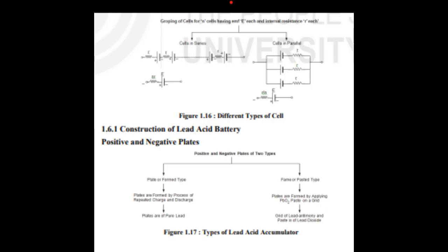1.5.2 Kirchhoff's voltage law, KVL. In any closed circuit, the algebraic sum of the voltages reckoned in a particular direction is 0. Conventionally, a voltage drop in the direction of traversal is taken as negative, while a rise in voltage is taken as positive. It may be remembered that across a resistor voltage drops in the direction of current, while it rises in the opposite direction, as shown in Figure 1.11. Thus, sigma V is equal to 0 round a mesh or path.